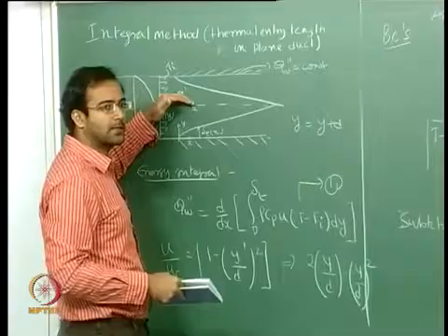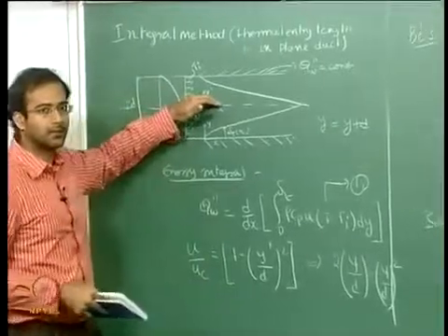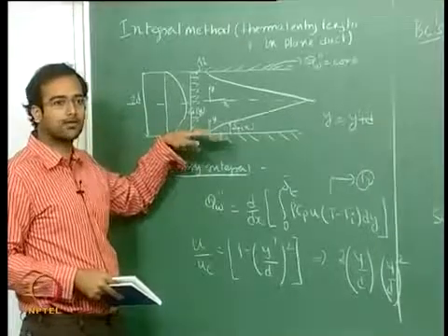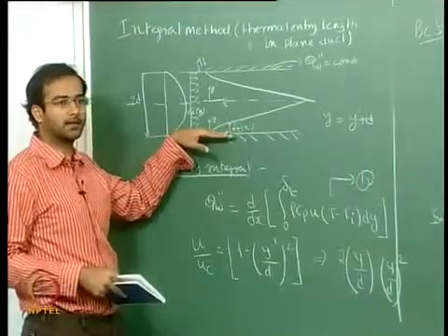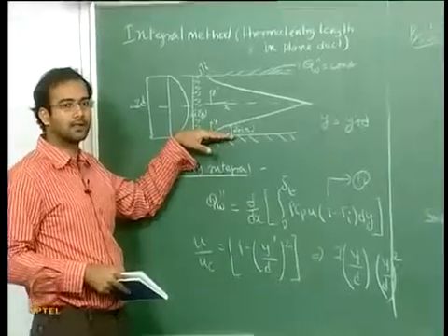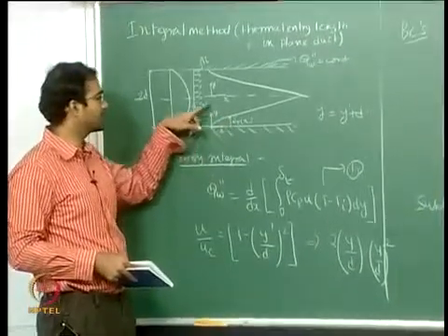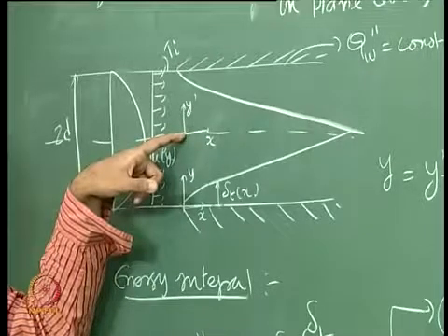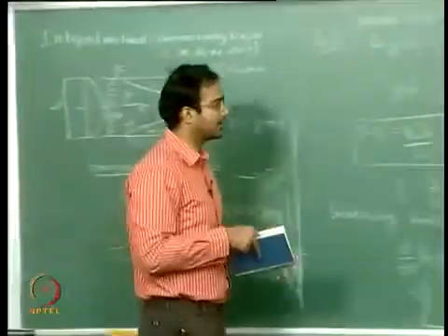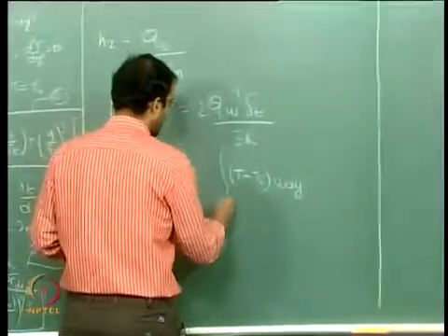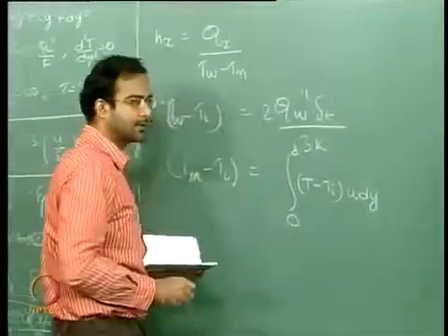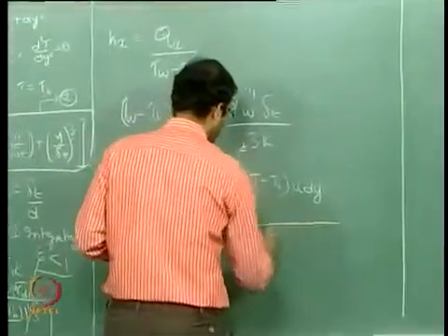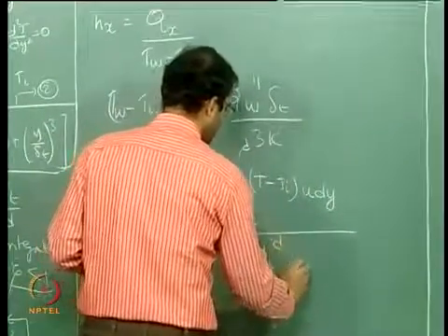Now the velocity profile that we have, we are looking at boundary layer growth from the top plate and bottom plate. Now we are focusing on only one plate at a time. So for this, the velocity profile we have to consider is from 0 to d, where you have your velocity profile, that is the maximum velocity there. So we will do this integration from 0 to d, because this is a mass weighted average we are taking, divided by integral 0 to d of u dy.